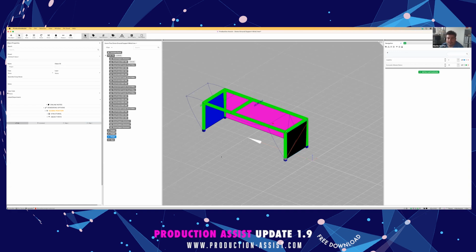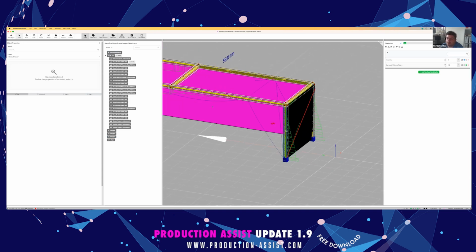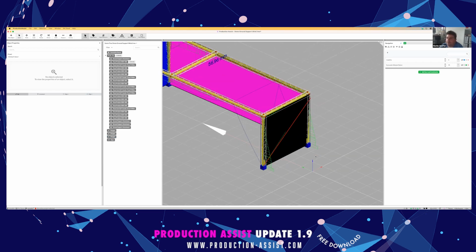One important note is that this is not a trivial calculation. I'll quickly show you this with the shear forces happening here. Because basically only 3 sides of the trusses are supporting this plane, the distribution of the actual load into the trusses is not really homogeneous. At the bottom, where the top truss is not supporting anything, a lot of load is put into the truss, while at the top, where the 3 trusses can support the plane, the load is shared a little more equally.